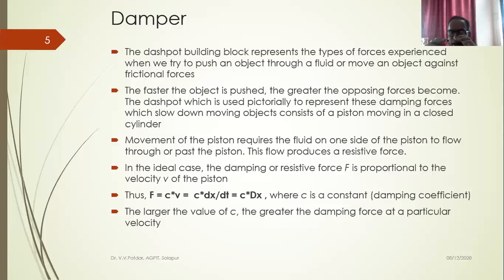So that air inside the tube provides the cushioning effect. So that air becomes my damping element. Plus the seat on which the rider is sitting has sponge beneath it, isn't it? So that also is doing the work of damping. Though it is not exactly a damper, it is a damper-like element. So I'll either have a damper proper, or I can have damper-like elements.